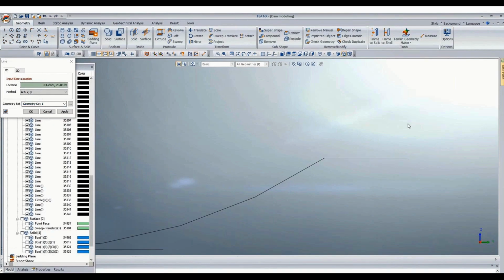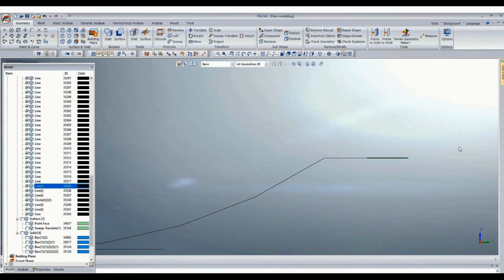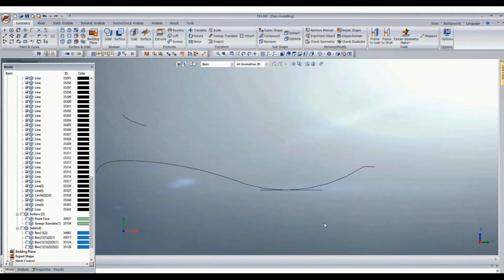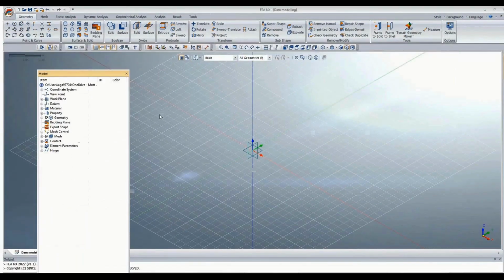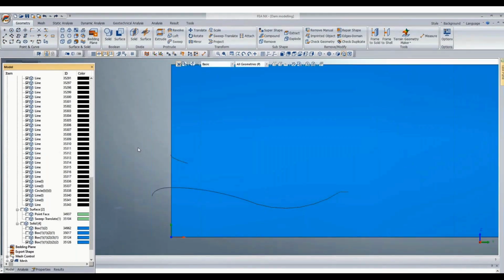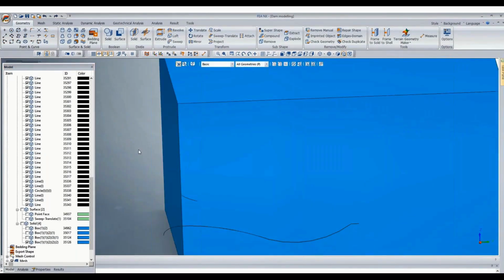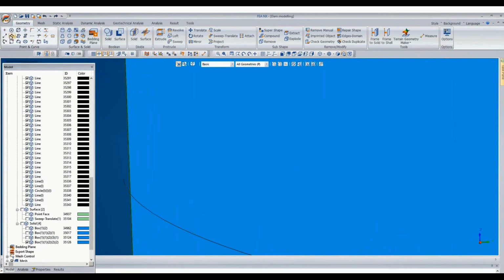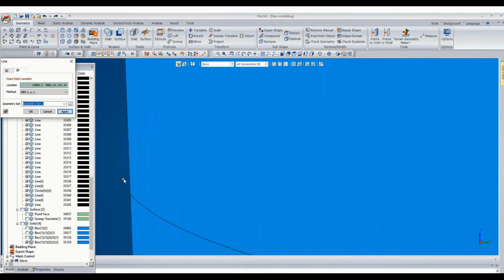Create this. Okay, so this will be my spillway profile as per the hydraulic calculations. Now let's put on that overflow blocks again, that solid block. Just have to move this profile a bit because this should lie exactly at the dam axis.